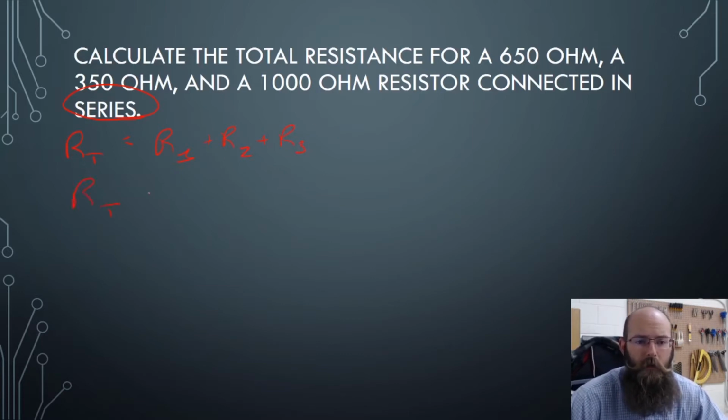So my total resistance is going to be just adding them all up, making sure that all of the units are the same, because we have 50 or 650 ohms, but sometimes I'll throw in milliohms or kilo ohms, and you don't want to mess all of that up, because technically 1,000 ohms is 1 kilo ohm, and you might just add 1, and that'll throw you all off. So be mindful of your units, and be graceful when it comes to my symbols in here, because some of these symbols get pretty tricky in electrical stuff.